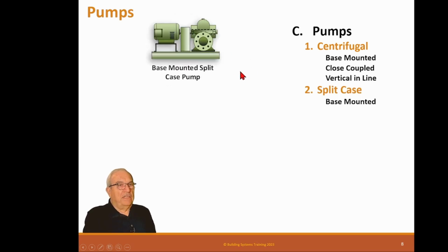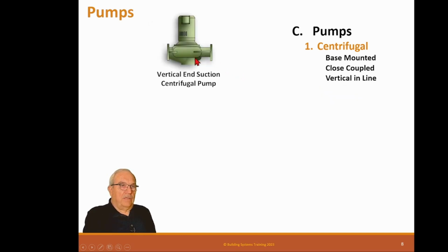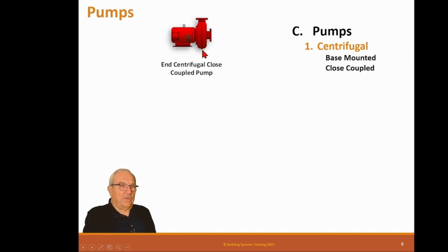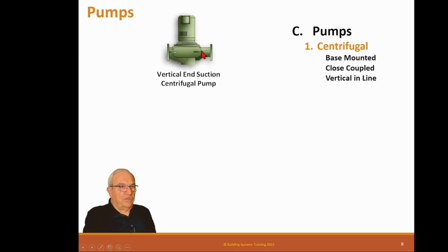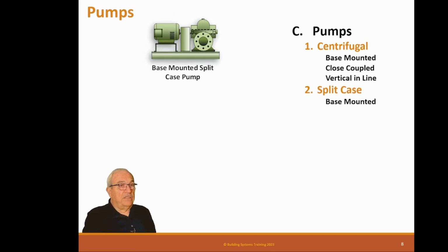Then we have a split case. Now, the regular pumps, these regular pumps are centrifugal pumps that are used for low flow, high flow, low pressure, high pressure. So those you can pretty much do anything with. These split cases are designed to move more water at lower head, but they can move a lot of water. I mean, you can get these in 24-inch sizes, pump a lot of water, but normally not up to the same head level we would have in a suction centrifugal pump.